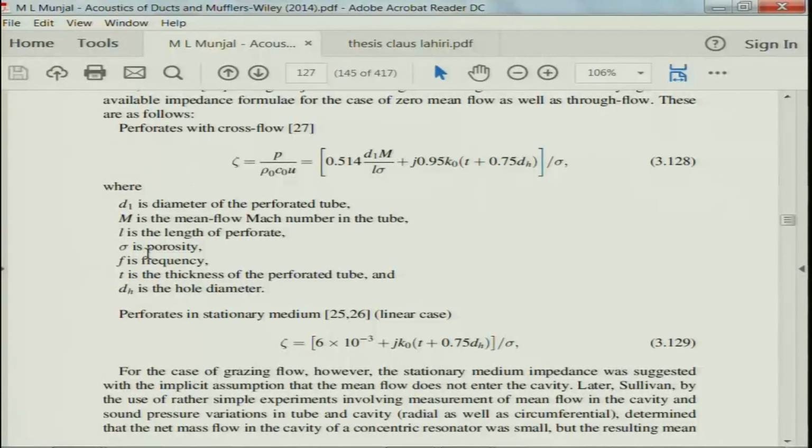So, one clever engineering trick that people use, if they want to maintain good aerodynamic performance and get rid of the flow-induced noise due to the flow expansion, is a highly perforated section, 30% porosity, so that the waves are allowed to pass through very easily.